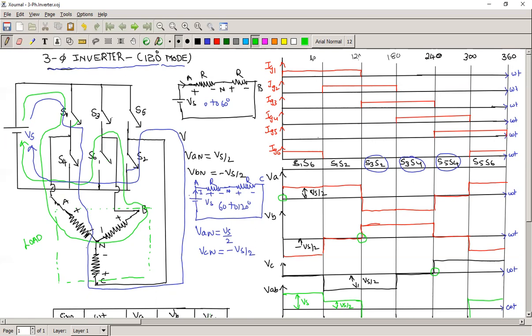But in the case of BJT, MOSFET and IGBT, whenever we withdraw the base voltage, the switch turns off suddenly. It does not depend on how much current is carried by the switch. So that's why, not only in the inverter but wherever the source voltage is DC, generally we go for BJT, MOSFET or IGBT, depending upon the power rating and switching frequency, at what frequency we are going to operate the switches.